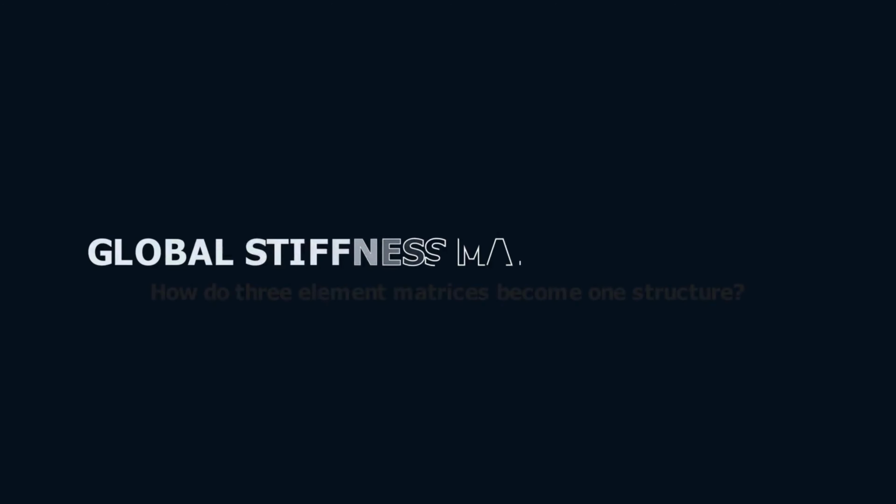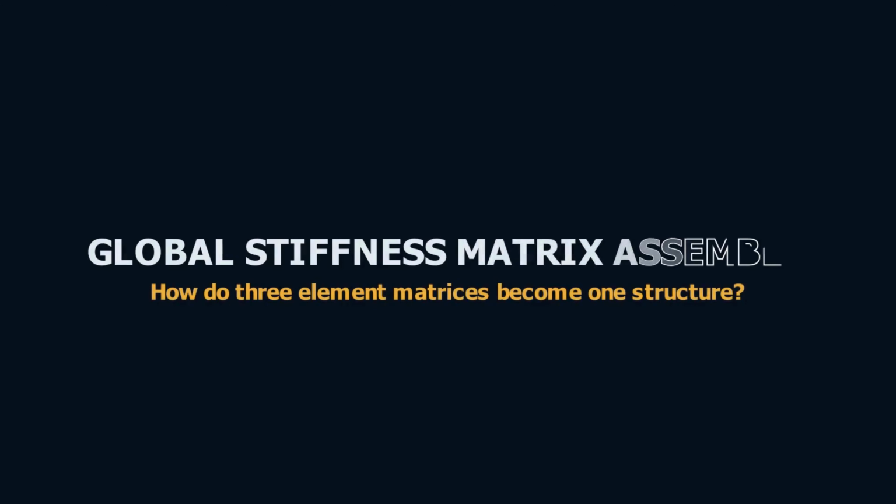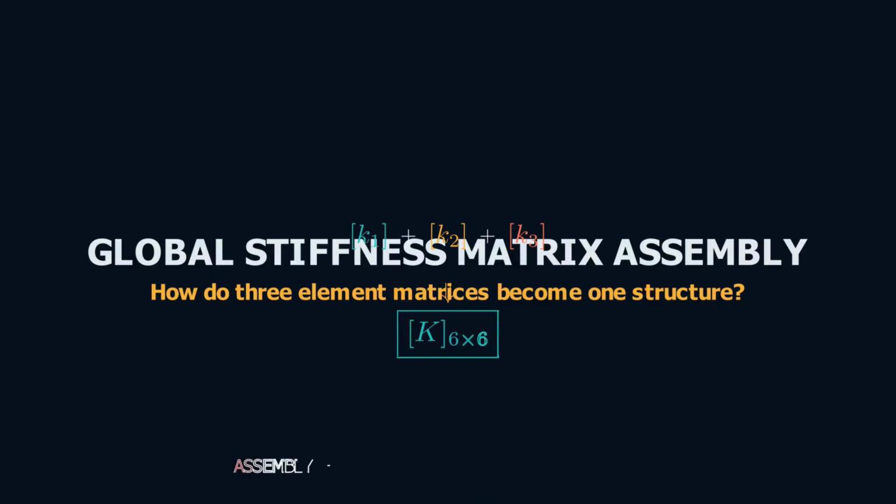In the previous tutorial, we derived the stiffness matrix of a single two-dimensional truss element. But our structure contains three members. So the next question is, how do their three-element matrices become one matrix for the entire structure?